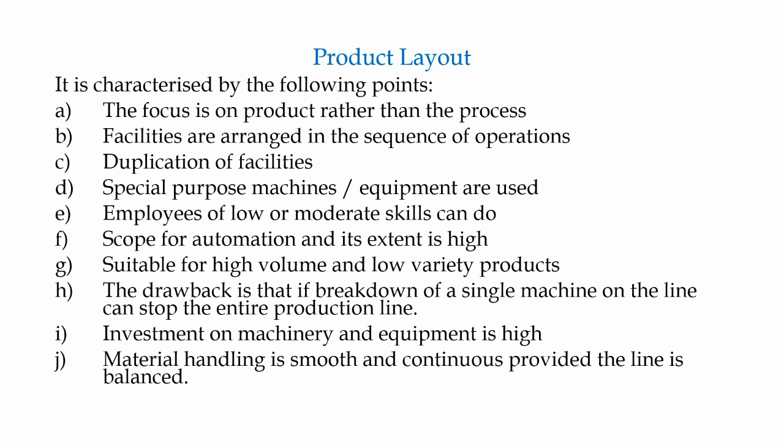Suppose, for example, drilling is an operation which is carried out at different stages. So initially we will have a drilling machine at one place, and the product will not come back to the same drilling machine for the next hole to be drilled. It will go to the next machine and next machine, and wherever the other drilling operation is required, there we will have another machine. As a result, we need to have multiple number of similar machines but at different points wherever the machine is required.